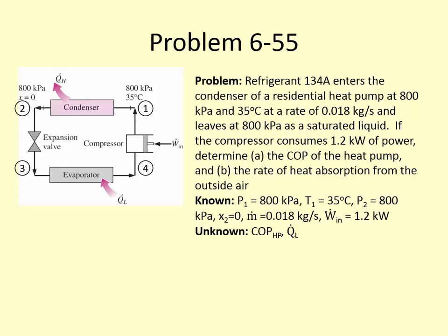And in this class, I know heat pumps are reversible and they can be operated as air conditioners, but if we're talking about it as an air conditioner, we call it a refrigerator. So it's a heat pump, and we're trying to make a warm space warmer, so our desired outcome will be the Q dot H, and then our required input will be the work dot in. So if we calculate the coefficient of performance, we're going to need Q dot H and work dot in.